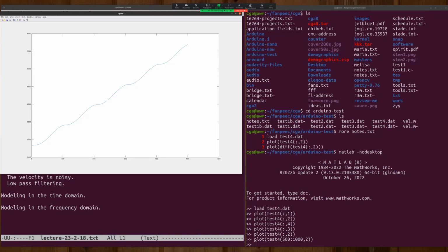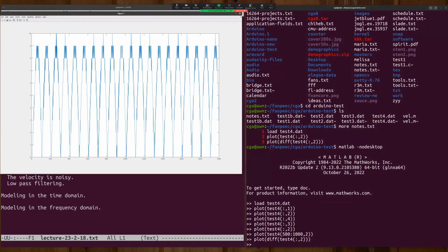Okay, so they're only giving us the A output, and what are we going to do? Well, I'm going to differentiate by subtracting the adjacent values. So this is what it looks like if you just add up the number of pulses. And this is what it looks like if you only keep track of how many pulses came in the last 5 milliseconds.